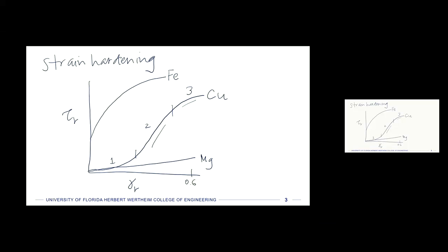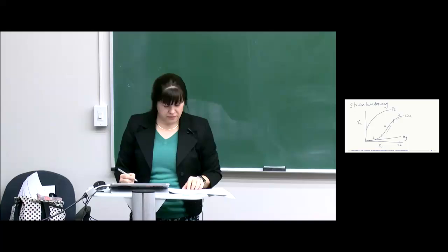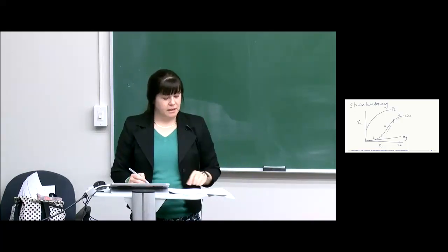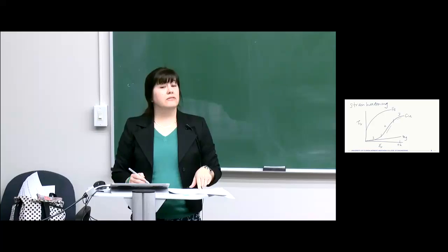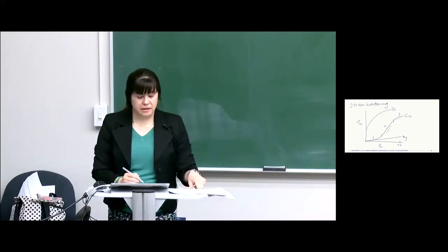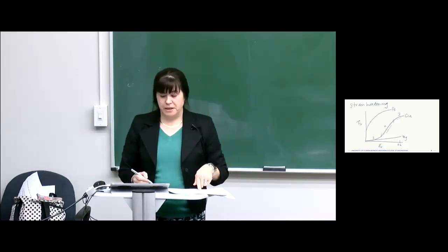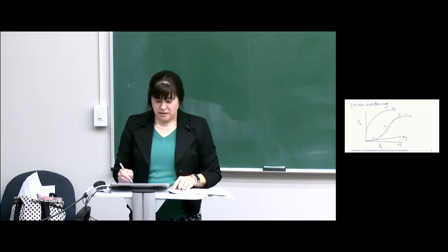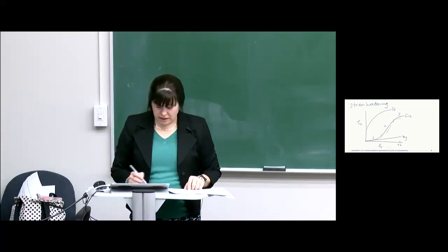So I'm going to anchor the x-axis by a value of 0.6, and so that is very high strain, right? And so this thing has slipped a lot, right? Usually we talk about the stress-strain curves for a tensile test, which we'll go over in detail, right? We define the yield strength on that as something like 0.2% yield, right? So this is 60%, so it's exceedingly high.